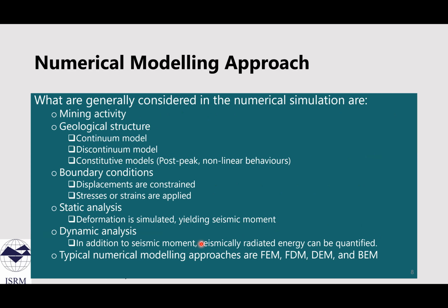So let me talk about the numerical modeling approaches. Over the decade, significant efforts have been made in modeling induced seismicity. So I summarize important points that need to be considered. First, we have to model mining activity. So we need to model ore bodies, and then we need to consider the sequential mining activity.